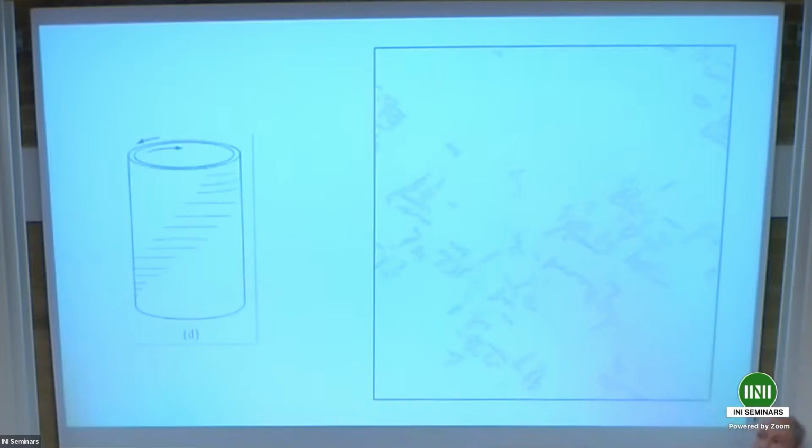Oh, I know what it is. What Matt did is he fit that by looking at the decay in actual plane Couette flow, and other people have done this as well. You look at what the effect of the boundary layer would be on the decay of those modes, and you match this alpha such that it would give you the same thing.